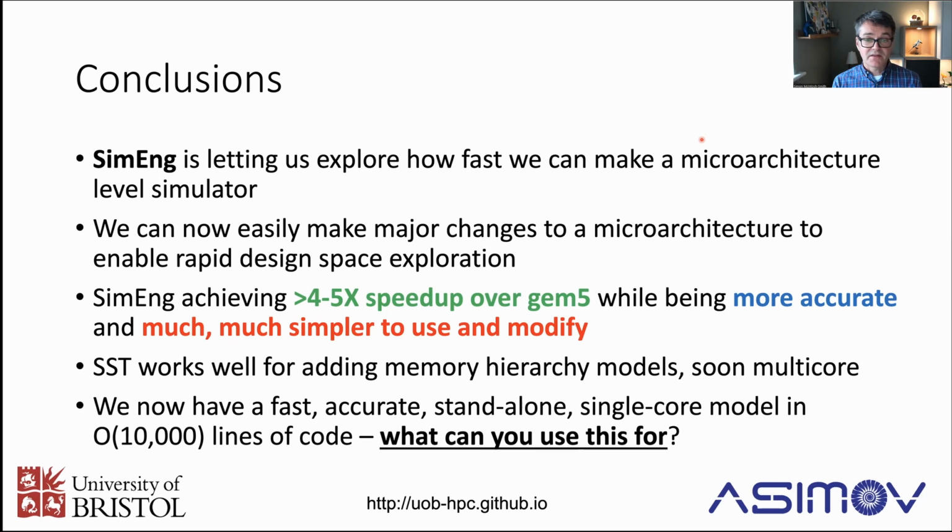It's quite interesting with, I mentioned SME, the Scalable Matrix Extension, where a coprocessor like that gets its data from. It doesn't really make sense for it to stream its data through L1, for example, because that tends to completely pollute and destroy everything in L1 that everyone else was using, when it's normally just streamed. So there's no temporal locality to data that you want to go through to a matrix coprocessor. So often something like SME, you might want to connect directly to, say, L2 cache rather than L1.